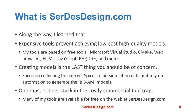Along the way, I learned that expensive tools kill all chances you have of achieving low-cost, high-quality IBIS-AMI models. My tools are based on free tools: Microsoft Visual Studio, CMake, web browsers, HTML, and more. I learned that creating an IBIS-AMI model should be the last thing you concern yourself with when it comes to creating IBIS-AMI models. Focus on collecting the correct circuit simulation and measurement data, and use automation. My tools rely on automation to generate models from measured and simulated circuit data.